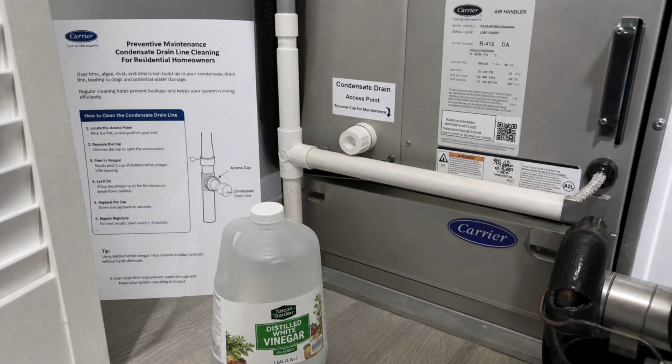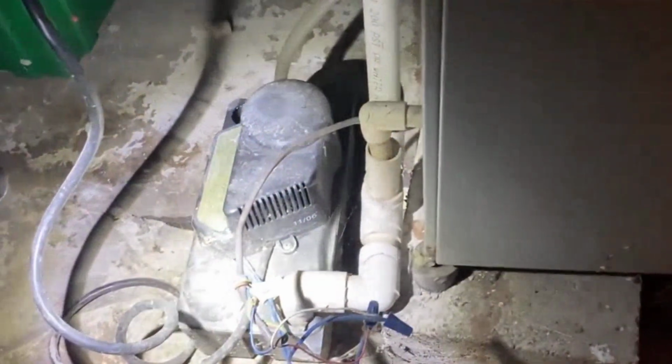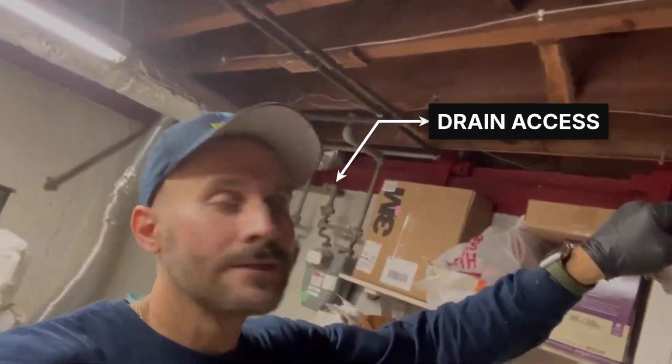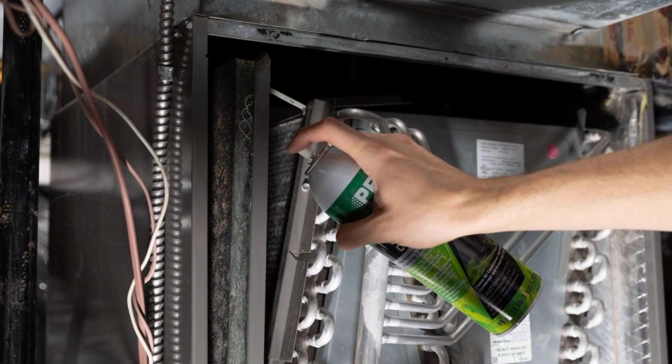Carrier tells homeowners to use distilled vinegar in a condensate drain. That instruction is public on the company's website, so the viral secret is already wrong. But Carrier gives vinegar one narrow job at an access point. For a clog, it points to a wet or dry vacuum. For a coil, it recommends another cleaning method.